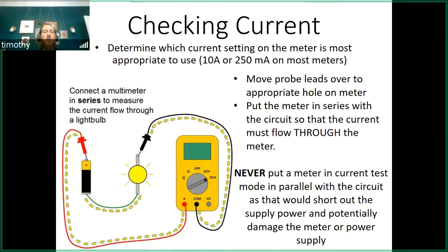Make sure that as you do this, you understand the current requirement, and make sure you never measure current in a parallel mode. Okay, never just touch it over it like you would to measure resistance. You will also have to power the circuit in order to accomplish this. So this is going to be working on a hot circuit, so use all the proper safety precautions.